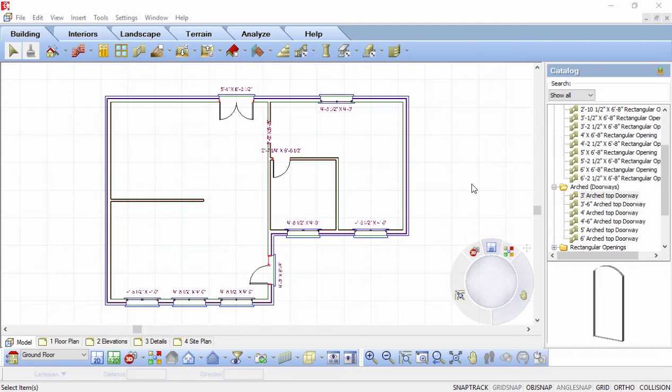By default, a floor is inserted automatically when you create a closed wall layout. Initially, the floor spans the entire model and then splits into individual floors as you create rooms inside the model. By default, the floor type inserted is a wood frame floor with hardwood flooring. You can customize floors in your model in many ways. We're going to change the floor in the bathroom to a tiled floor.